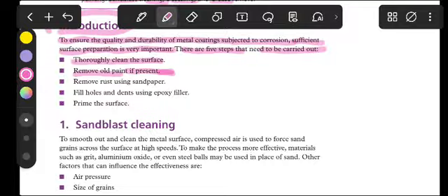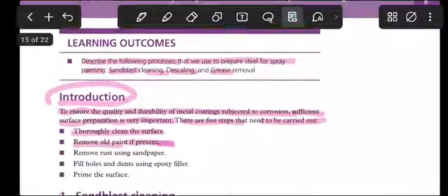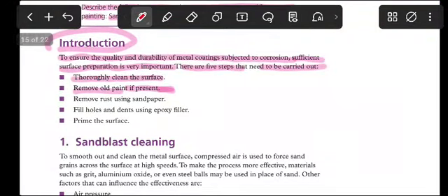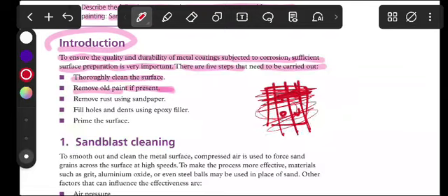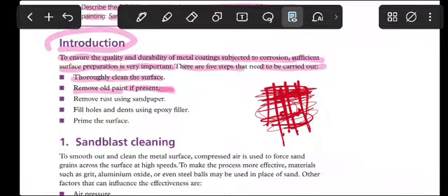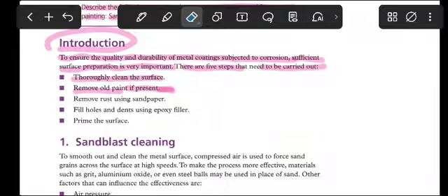if present. Remember preparation. Let's say you want to paint the wall. If you are painting an old house, old building, there'll be little patches of old paint. You must scrape this off, you must remove this and be clear. Then lay your new paint. Clean the wall or whatever you are painting. Clean that metal, doesn't matter. If you're painting the door, clean it first. Do not just paint.